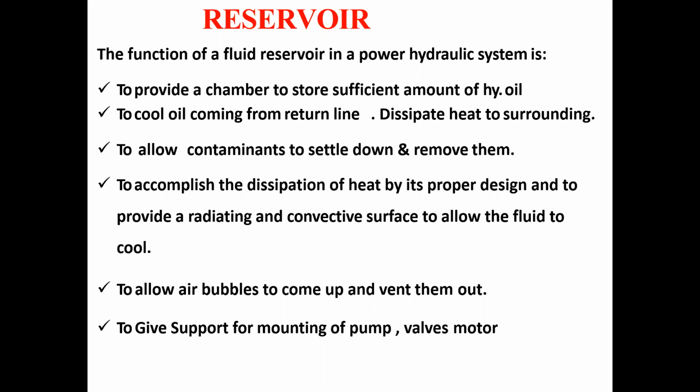So what is the function of reservoir? To cool this high temperature oil coming back from the system to the reservoir, so that the system remains cool. For this purpose, it is required to dissipate the heat of this oil to the surroundings. Dissipate means to pass the heat to the surroundings. The meaning of the word dissipate is to transfer or to pass.